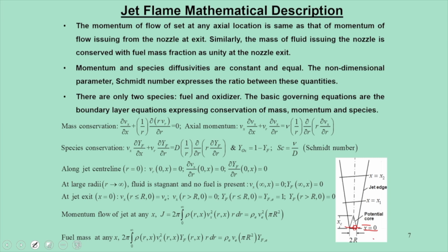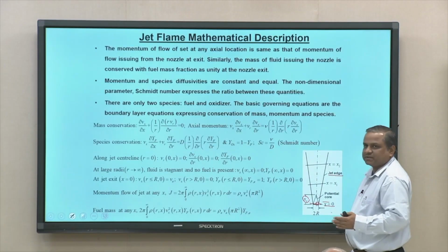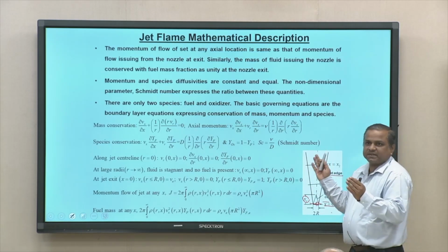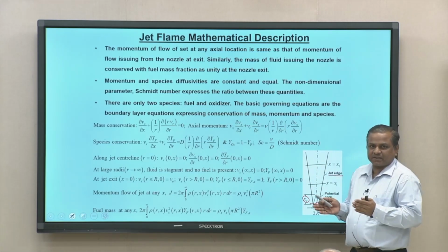First, the potential core stands with a standoff distance which is xc, and this xc talks about the peak point of this initial conical potential core. And when the jet spreads, there is a partition. We call this the jet edge, which means that these are imaginary partitions, because there is no physical partition.